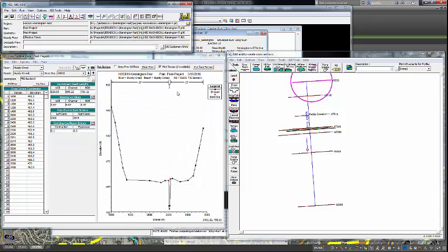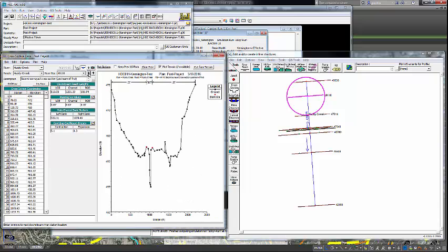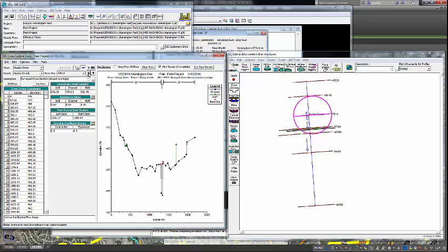Now what's going on here is you see the geometry file. Ahead of time I have set up cross sections of this creek. If I click through it, we can walk down the creek bed. There's not a lot of data points here, so you can tell that it's kind of rough, but you get the idea of where the low points are and where the water might flow. You can see over here that we're moving downstream. I just drew in a line and put in these cross sections, so this isn't as pretty as it could look, but it still does the job.